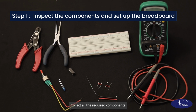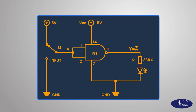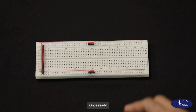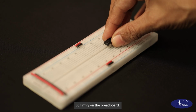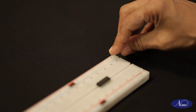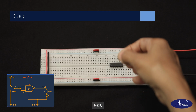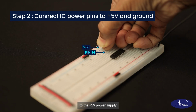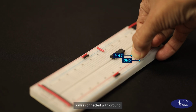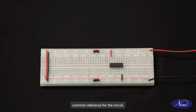Collect all the required components. Ensure the resistor and LED are in a working condition using a multimeter. Once ready, mount the 14-pin IC firmly on the breadboard. Connect linking wires from the power supply to the breadboard. Next, connect 14th pin of the IC to the plus 5V power supply. Then, make sure pin 7 is connected with the ground. These connections are vital for providing the necessary power and establishing a common reference for the circuit.